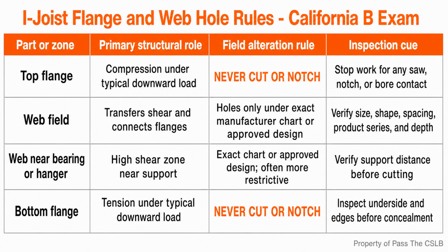The flange rule is the cleanest one to remember. Do not cut or notch the top flange. Do not cut or notch the bottom flange. A saw kerf, a plumber's notch, or an oversized drill that touches a flange is not a small web opening. It is a flange alteration, and I stop the work.